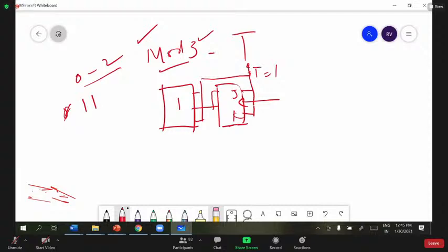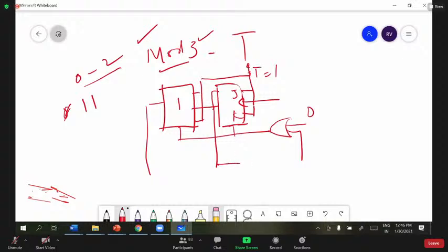Okay, what do you do then? AND gate is applied to the T outputs. That means, initially you are using this clear, right? So this is the clear. Okay. So initially we said clear is made high, and we have kept that as 0. So as it is, we can take this and connect to the AND gate directly, and this is 1. Okay. So one of the inputs of this one means this is 1. We can reset all the flip flops.